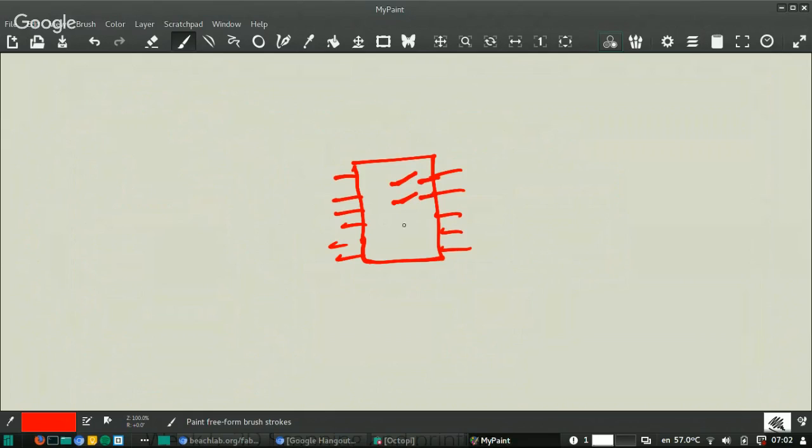You only need this. This is the microcontroller. And you have to think about something that you can control by software, a lot of switches here. Every pin is like a switch that you can control in software. Okay? This can act as an output. It means you can control this and you can deliver either 5 volts or 0 volts. That you can control later in software, this switch.